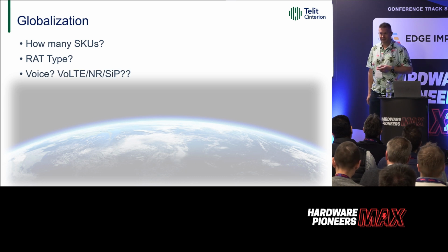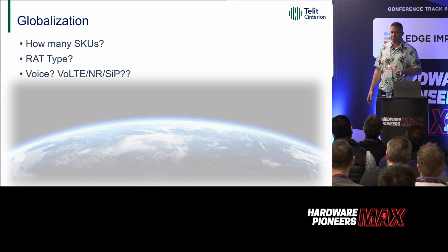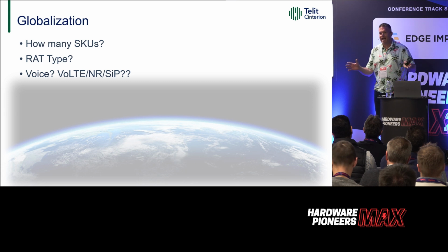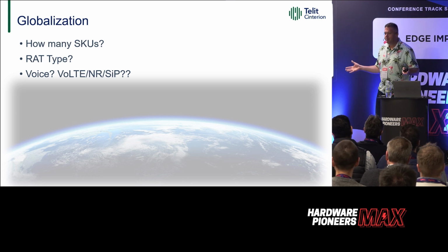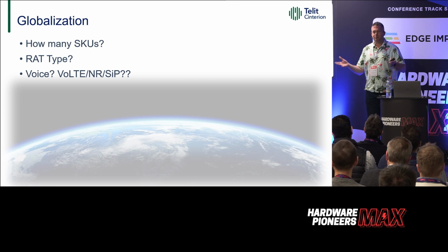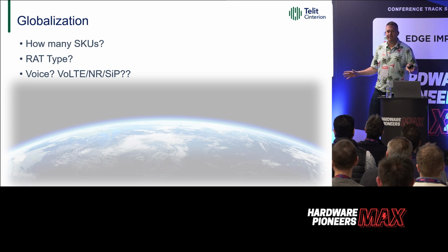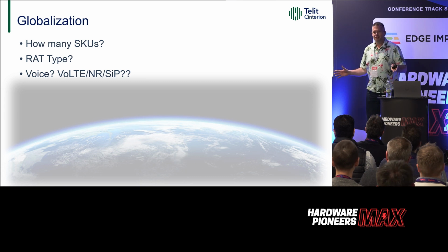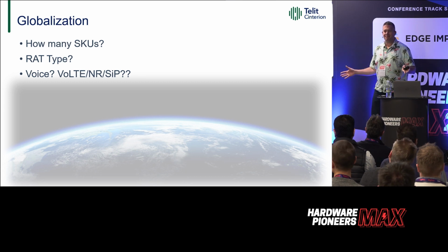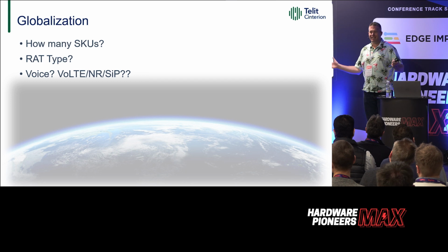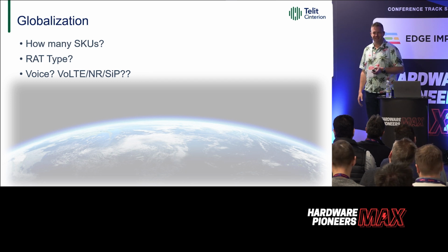Do you need voice? I know it seems like a silly question, but there are people in this room right now who I know for a fact use voice technology over cellular. And you might hear Cat-M has voice capability. Well, that's marvelous, except there's basically no network operator in the world that has launched it, save for Swisscom, I think. So can you make a global device on Cat-M that uses voice? No, because you're not really going to get a global solution out of it. Okay?